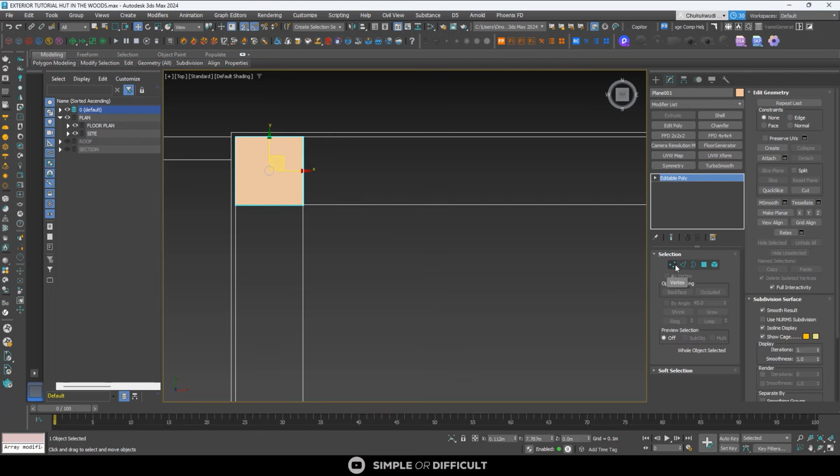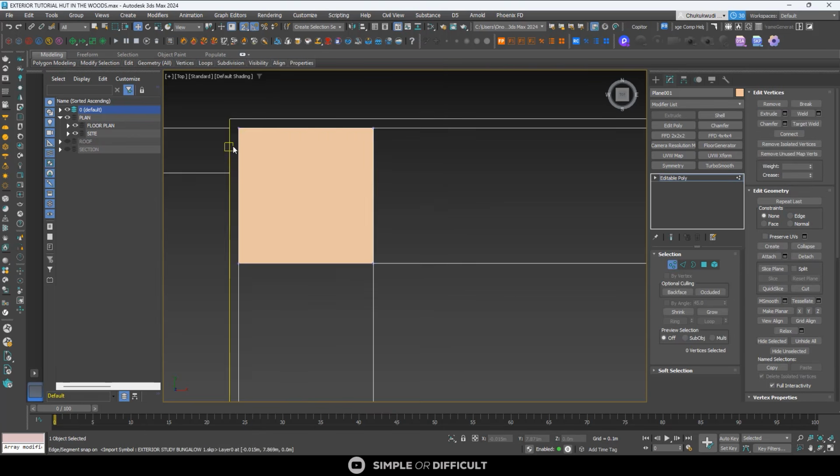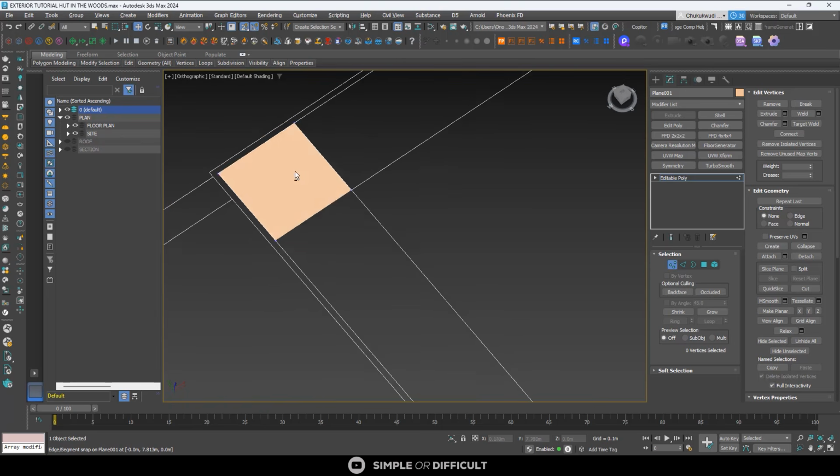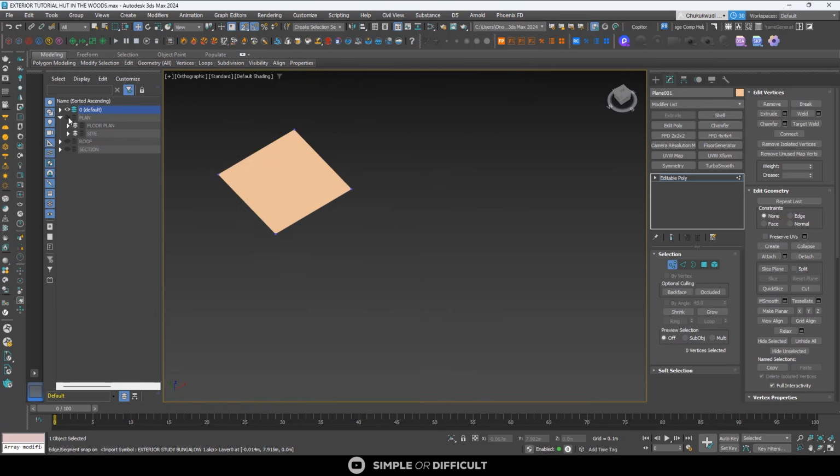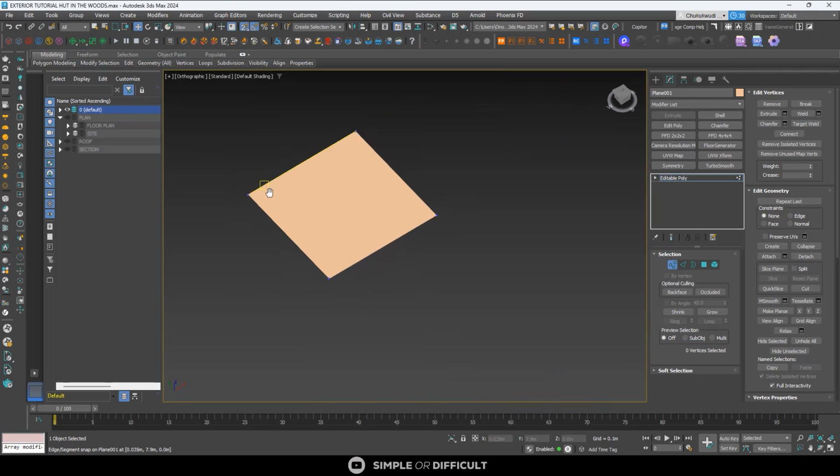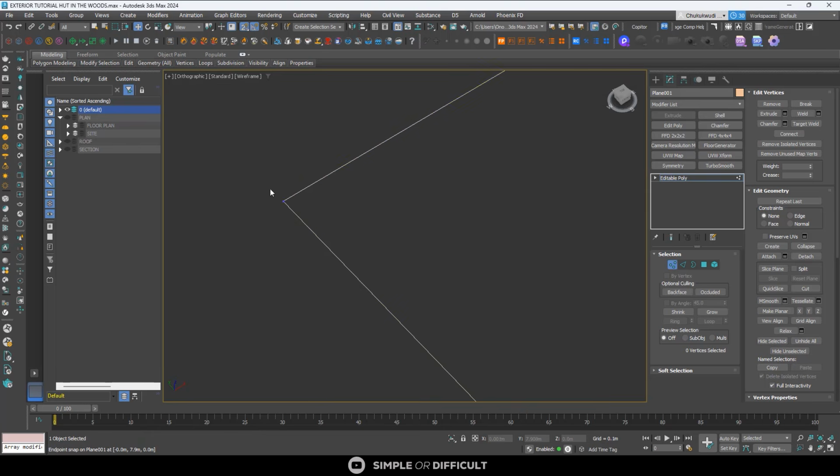You can select and move it around. You can see selection. You can see vertex mode. When you set vertex mode, it is going to add points. Let me put this in 3D mode. Let me turn this thing off so you can see it. Let me put it in wireframe mode. You can see the points active. If I select a point, I am selecting the point. No matter what I do, it's just those points that I will be able to select.